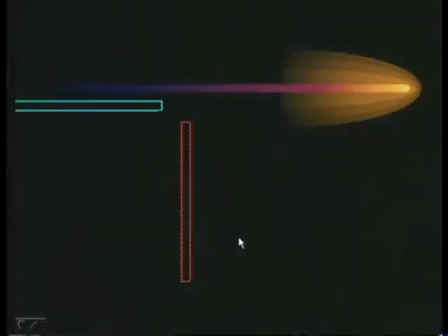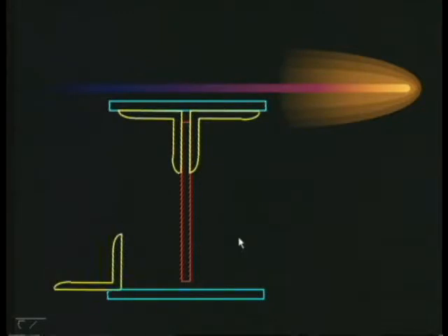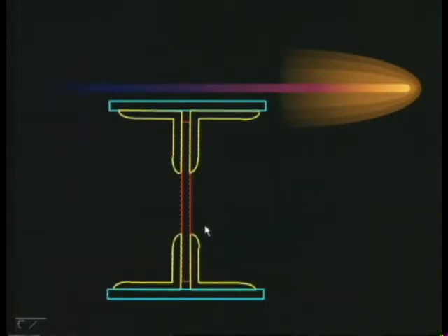You want to see another one? See here. Yes. You need a section which offers more section modulus. Take a web plate. What are these plates called? Flange plates. These angles are flange angles. If you observe it keenly, you can find a gap here. Just guess, why should you have a gap here?